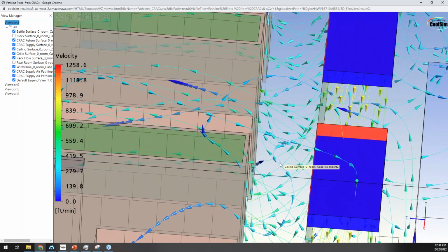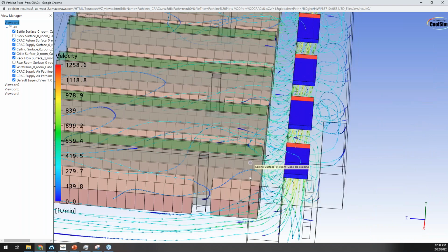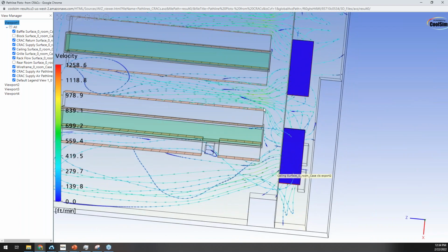One of the things to be careful of in these kinds of designs is velocity profiles at this end of the rack. These are pretty close to these cooling units, and as a result, this velocity will be high. High velocity again means low pressure. So as I mentioned, the pressure's building in here, even though we're supplying more air to the room than the full racks need. The local effects will have importance.